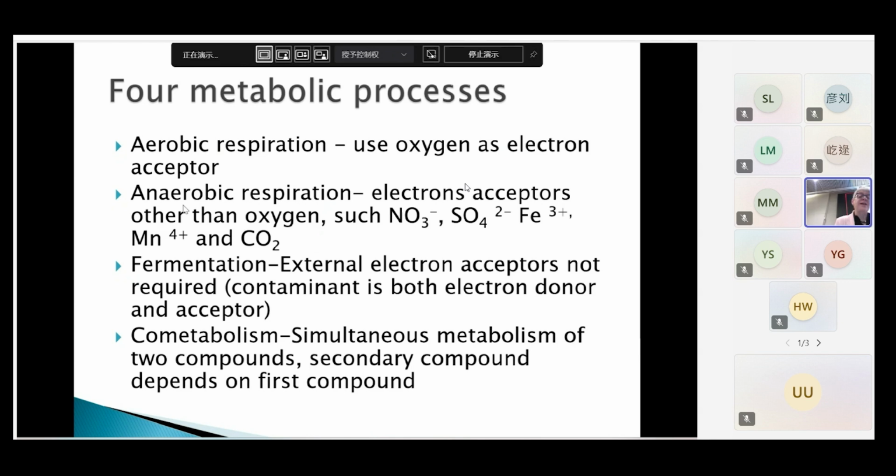So thermal extraction is basically heating your soil, and so you can use things like fiber optics. You can use various types of radio frequencies, hot air, steam injections, all sorts of things to increase the volatilization of contaminants in the soil. So basically the idea is that you're bringing up the temperature, it increases the volatilization. So it works well with organics, works well with methyl mercury, and things like this. You can also incinerate your soil, which is also quite a frequent use for highly contaminated soils. Things like dioxins and things like this. You obviously need very high temperatures to do that.